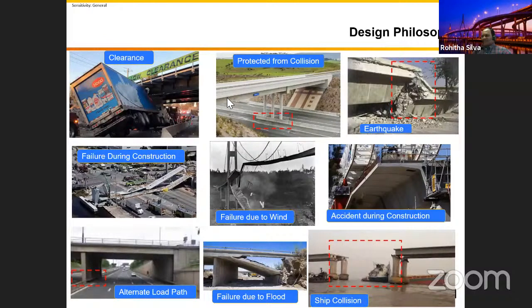You can see this is a bridge going above the road. There are barriers protecting these three small circular columns. So the designer might consider that if there is an accident, they want to protect that one. Sometimes the designers can design this so that even if one column cracks, the bridge won't collapse. They can go back and fix it. So we're going to learn this thing today.